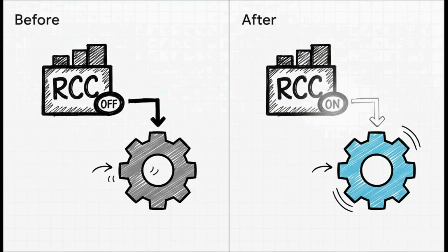Okay, listen up, because this right here is the single biggest mistake that almost every beginner makes. To save power, every single peripheral in our city starts out with the power turned off. The power utility for the entire chip is a special unit called the RCC, or Reset and Clock Control. If you want to use a peripheral, you must first go to the RCC and turn on its clock. If you forget this one step, your peripheral is a brick. It will do absolutely nothing.